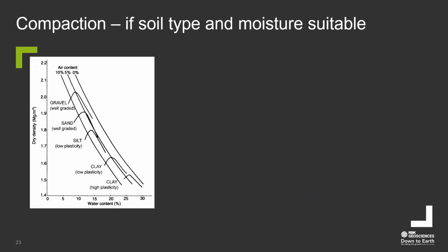Compaction, again, I'm going to whiz through these relatively quickly. Standard compaction testing on soils from investigations will show you the relationship between the moisture variation of a soil, and there'll be a peak value, the optimum moisture content, which will tell you the theoretical maximum you're going to get for idealized compaction, and that'll give us, say, 4% void space, which is a 96% compactive situation.